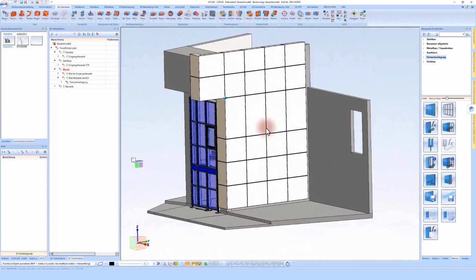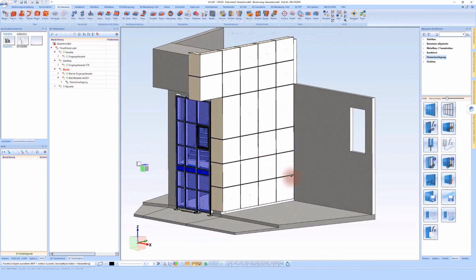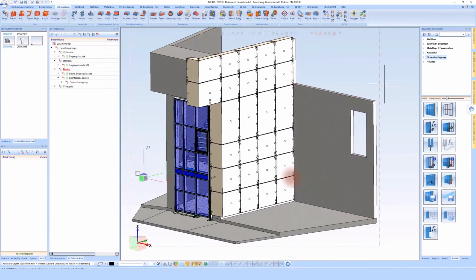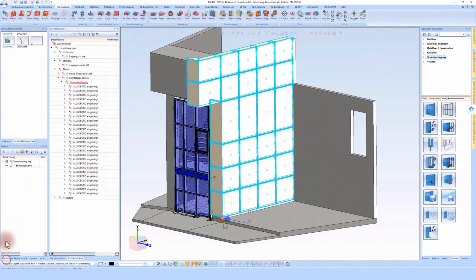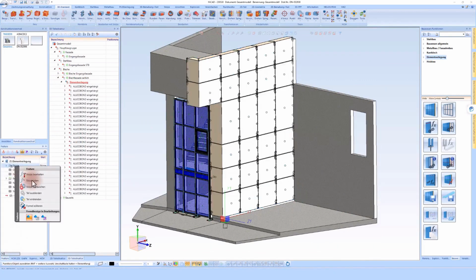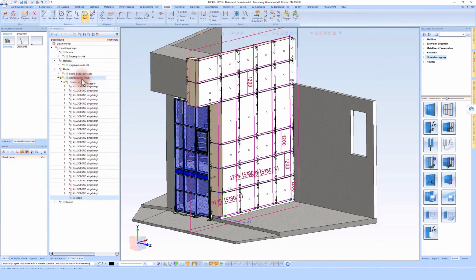In the next step, however, I would like to set the substructure as well. For this, I will load my sketch from the element facade here. This means I want to reuse the same sketch. To do this, I can right-click here to load this sketch and pull this sketch to the side in my sheet facade.